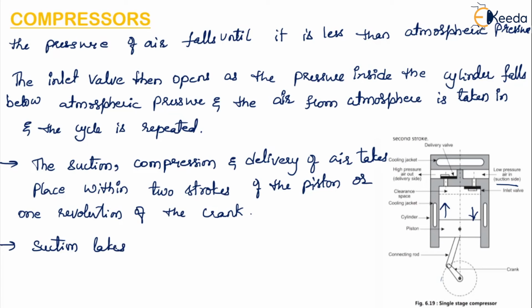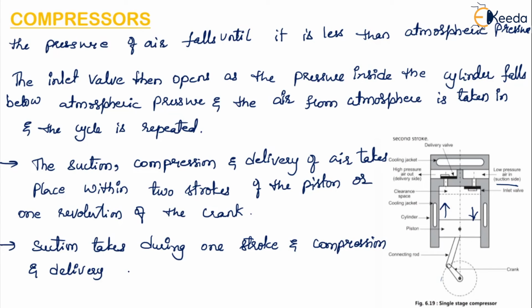Suction takes place during 1 stroke, that is the downward movement of the piston, and compression takes place during the 2nd stroke, that is during the upward motion. Compression and delivery takes place during the 2nd stroke.